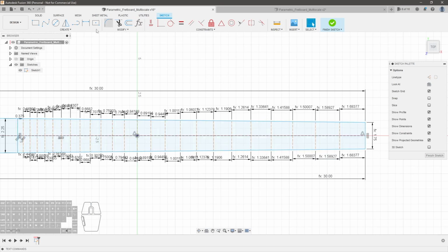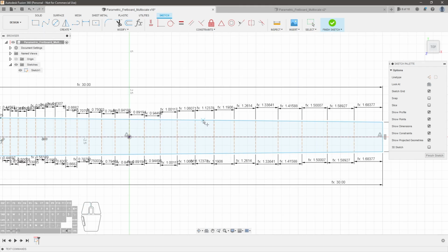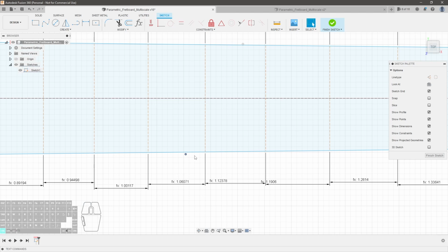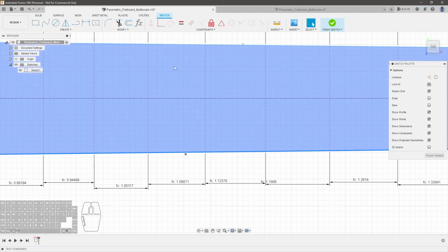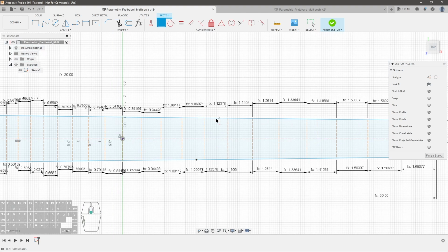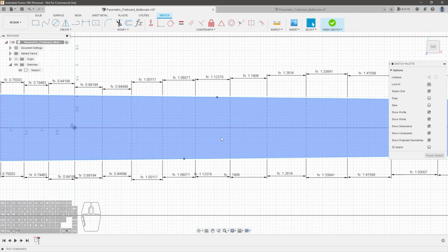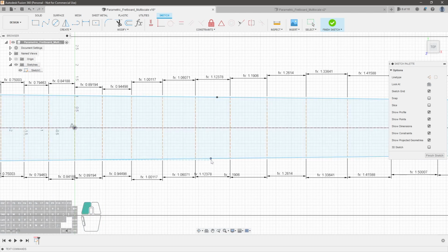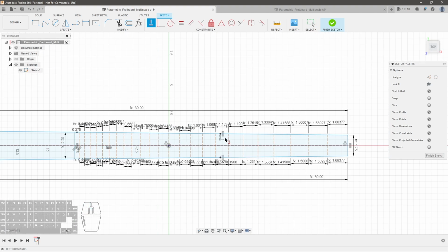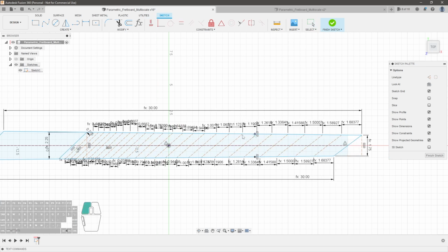And the way this works is you create a point anywhere, doesn't matter where you put it, anywhere along each edge. So let me put it here and here, for example. Now you'll notice I didn't make that coincident, and these need to be coincident to that line. So I'm going to apply a coincident constraint, and this one was the same thing. Apply a coincident constraint to that line. Now, the other thing that is required in this is each one of these has to be vertical to each other. So if I select both, I can come up here and hit vertical.